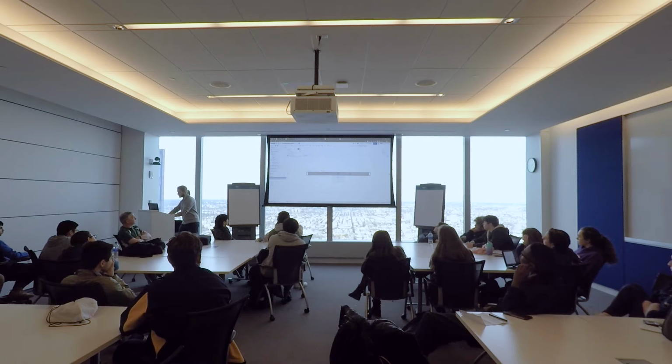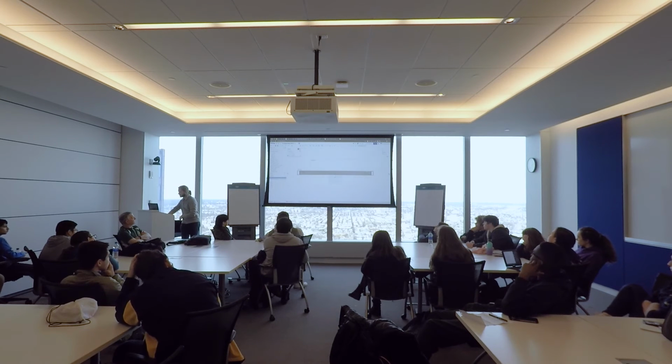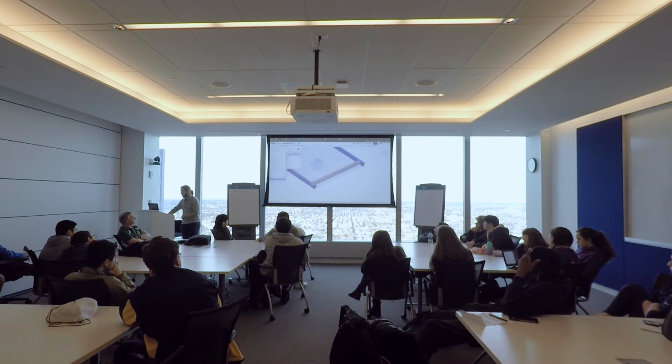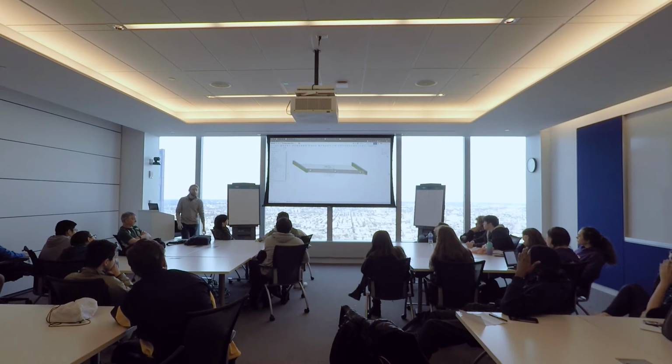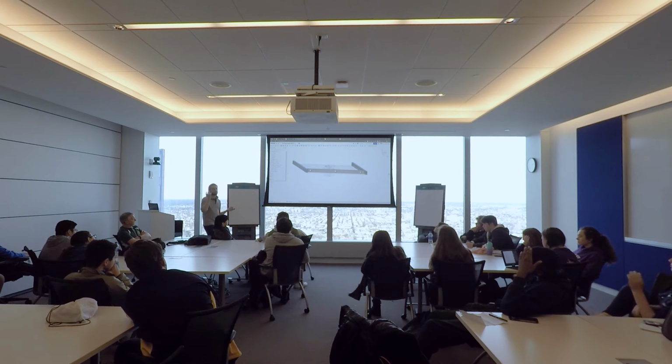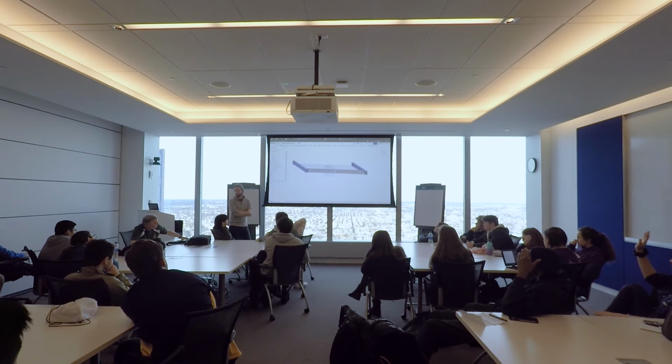We make this one coincident with that one. This one coincident. Got to make sure you select the right one for stuff. And this guy here. And you can also mirror this left to right too. It's an option. Then you can just extrude, remove away where your bearings are. Just do extrude all. And there you've got exact locations of bearing holes for a standard West Coast drive with exact center to center spacing. So if only it was easy to drill holes then.